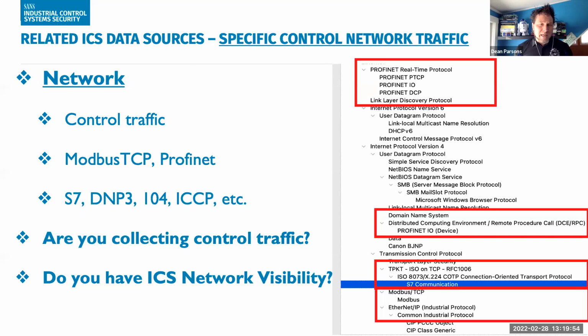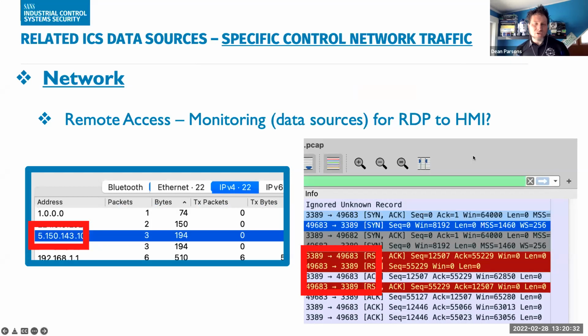So what you see on screen here is just a packet dump from Wireshark. It's a PCAP from a plant network. Now it actually shows us the types of traffic that's in there specifically related to industrial control. So we do see Modbus TCP and so on and so forth. And again, this is an example of how, at this point, with just a simple tool like Wireshark, you could do hunting going beyond just the IOCs, which could be just a port number and an IP address. Now we can look at the types of commands on the network, which may be related to command abuse or some living off the land, which we have seen in our sector several times now in the last couple of years. So just an example of this from the network perspective,